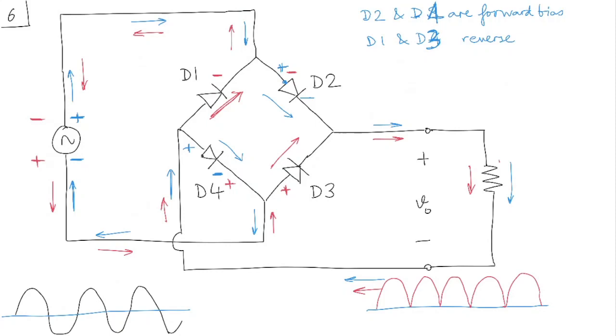This is basically a rectifier circuit, but this is called a full wave rectifier. In the class we did a rectifier called the half wave rectifier because it cut off the negative half cycle. But a full wave rectifier is basically taking the absolute value of the sine wave. It shifts the negative half cycle, or mirrors it, onto the positive side of the axis. Hopefully that makes sense.